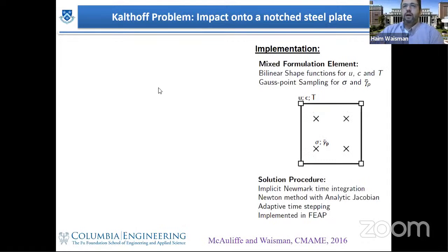So now if we go to the implementation, we will have, again, a mixed finite element formulation. At every node, we will have displacement, phase field, and temperature degrees of freedom, while at the Gauss points, we will have stress and plastic strain degrees of freedom. The system is solved implicitly and integrated using the Newmark method, where at every time step, there are nonlinear iterations that are solved in order to converge and move on to the next problem.